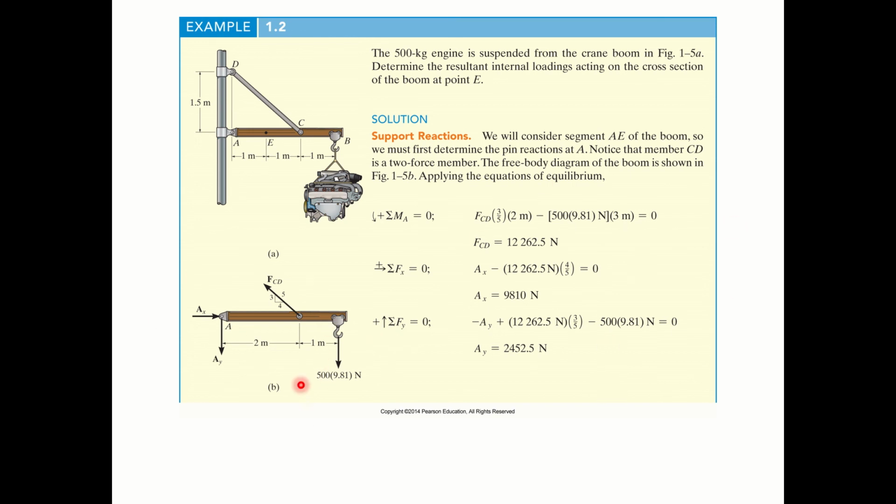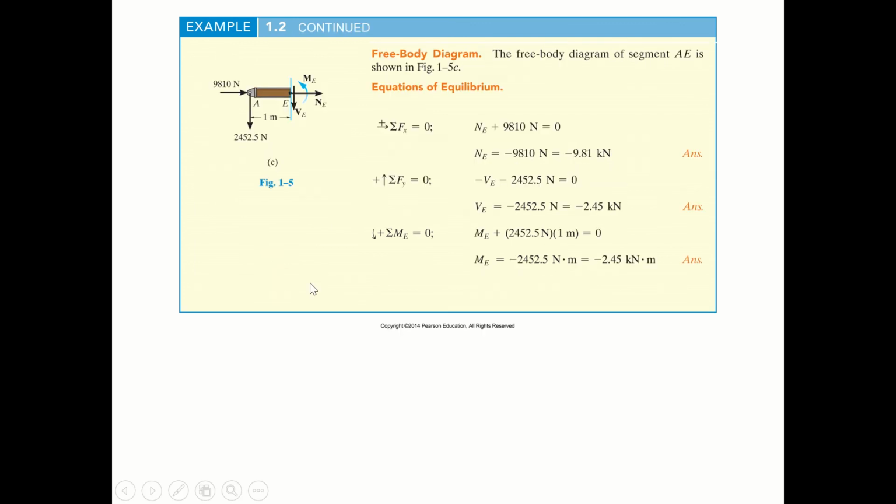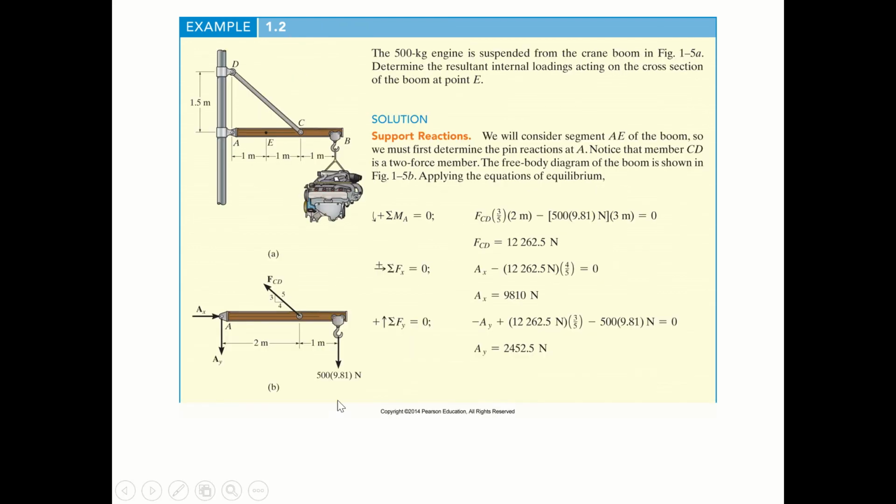You can obtain the relation between AX, AY, and FCD. Okay, and after you obtain AX and AY, you could use the free body diagram. Okay, you could cut it off along the E point.